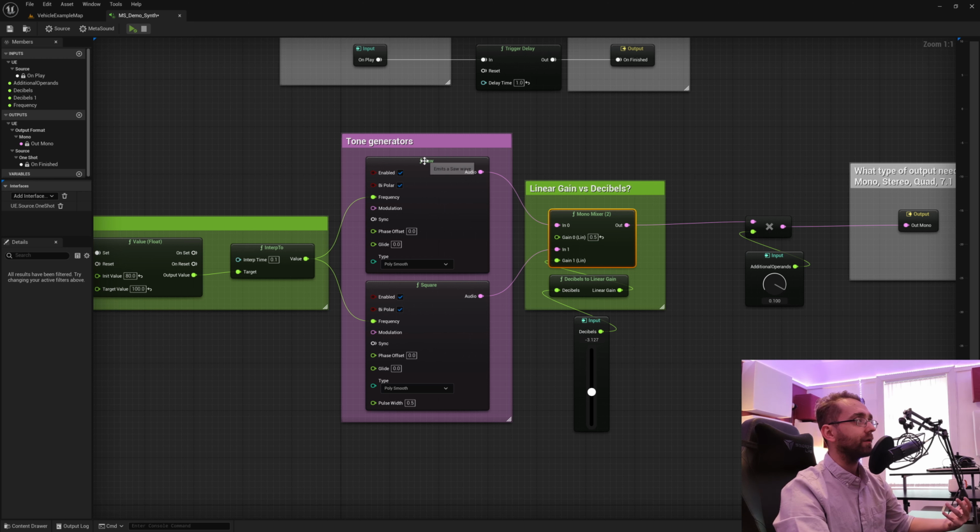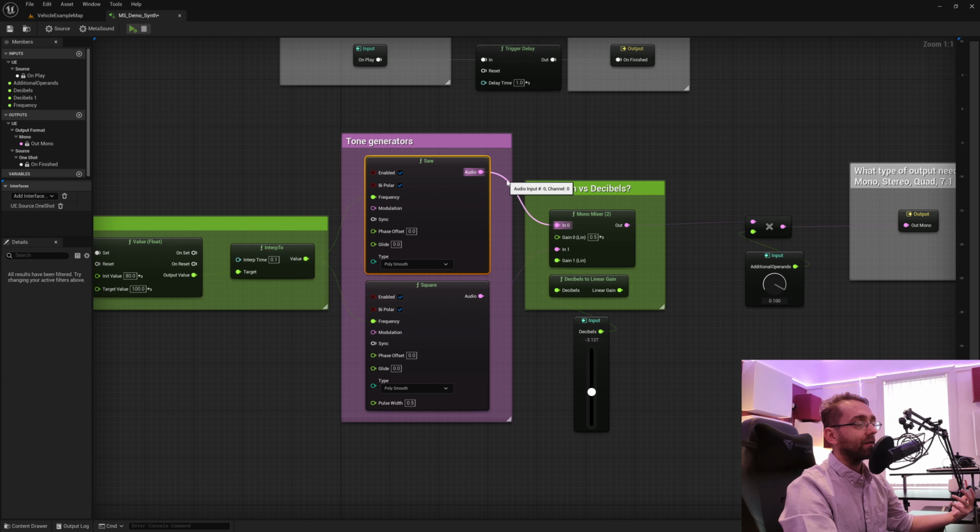So if we say, for instance, let's talk in terms of voltages. Let's say out of this audio here, we have a saw wave, which has an amplitude of plus minus 2 volts. It's coming in here, and we say, well, we want 0.5 of this signal to be mixed in with this, which is a way of saying we don't want 2 volts, we want 1 volt, which will eventually come out of here from this saw wave.